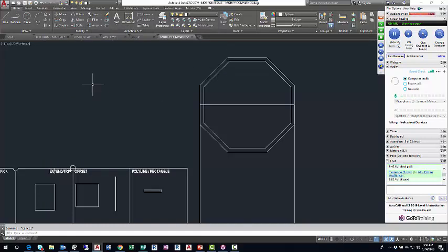First, we start the command. Second, enter number of sides. Third, define a center point, left click somewhere for a center point. And then choose your option. You either want to measure from the center to the pointy part, center to the vertex, or you want to measure from the center to the long angle. Long angle is circumscribe. The vertex or the corner is inscribe. But at the end of the day, if I hover over this thing, it's a polyline, not a polygon, a polygonal polyline. It's a multi-sided polyline. Okay, so those are your advanced draw commands.